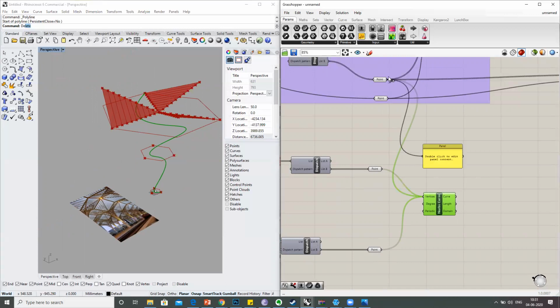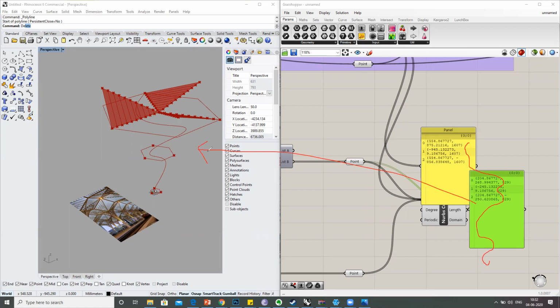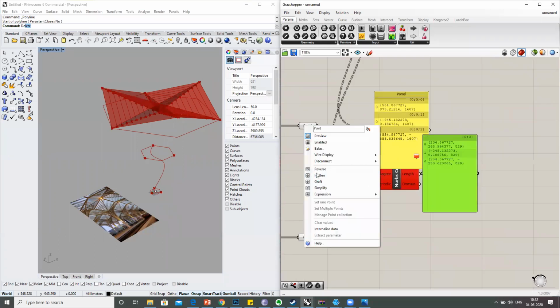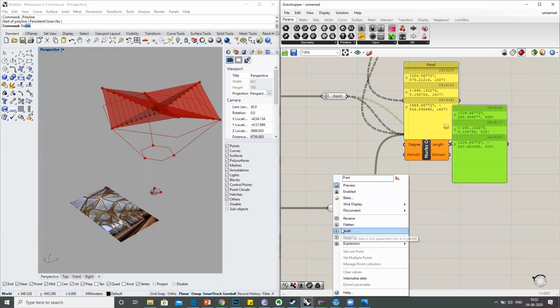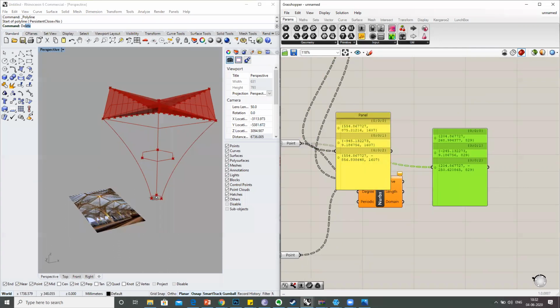That is because if you take a list, you'll see that this is a single list. And then this is a single list. So what happens is the curve starts interpolating, or making a control point curve from this point, this point, this point, this, and again the last three. That results in your singular curve. So what we need to do is split all of those. So I'm going to make a quick graph. So if you see, you've got 3 different lists. I'll graph this also, and I'll graph this also. So see, now what happens is this gets connected to this and this gets connected to this, in the third list, this to the third list. So you imagine you have another list which connects back to this point.